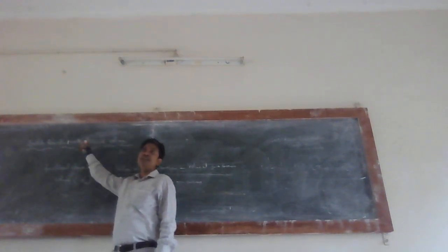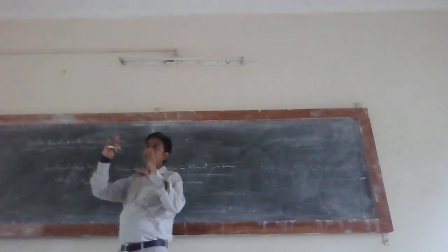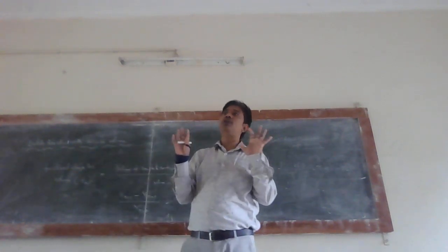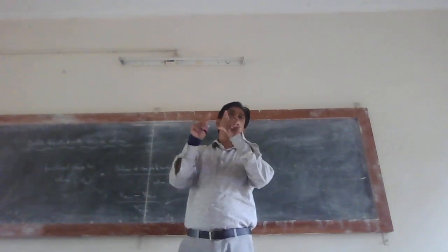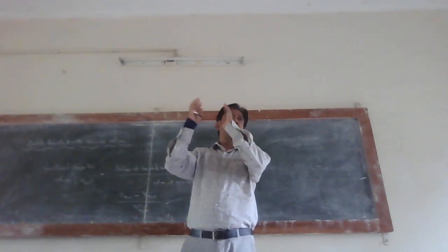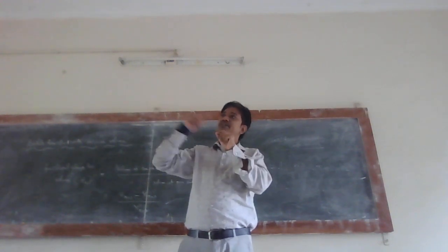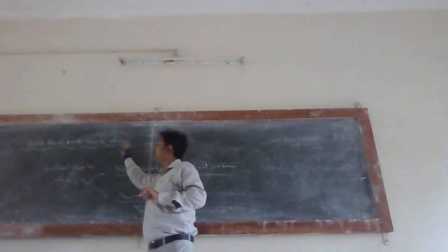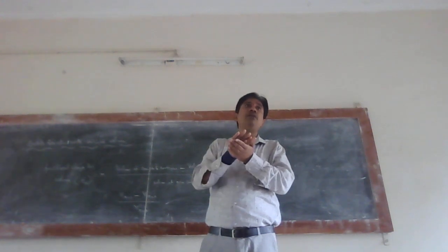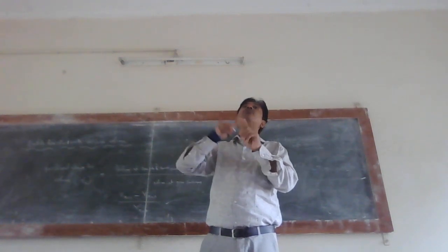Whenever any volume is varying. Till last class, we learned the concepts of constant volume, wherein V is constant. That's why you took V inside the derivative, and minus rA equal to 1 by V dNA by dt became dCA by dt. But now volume is varying. That means the volume with which you started the reaction will not be the same after some time or after completion of the reaction. So your initial and final volumes are going to change.